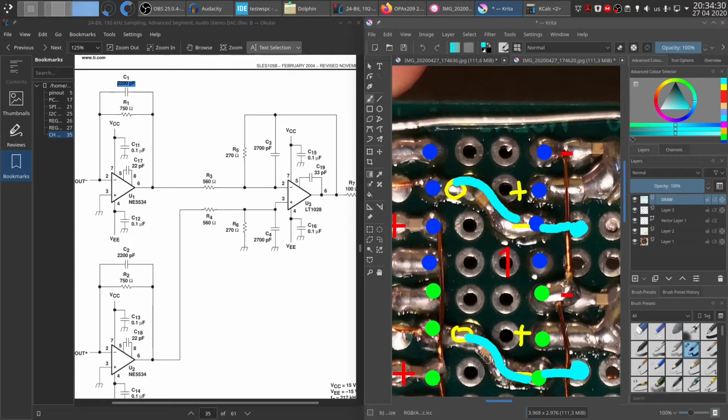This is why I like SMD very much for prototyping, because this SMD, in this case 0603, but 0805 would also be good, are just large enough so you can bridge different solder points on this standard 0.1 inch header board, and you can just connect them like this and have a little circuit connecting them together. So that's why I really like them. Plus they're not the smallest package, so they're quite easy to work with using tweezers. Also they are small, which is fine, because if you think about all these components being through hole components, this would waste lots and lots of space.